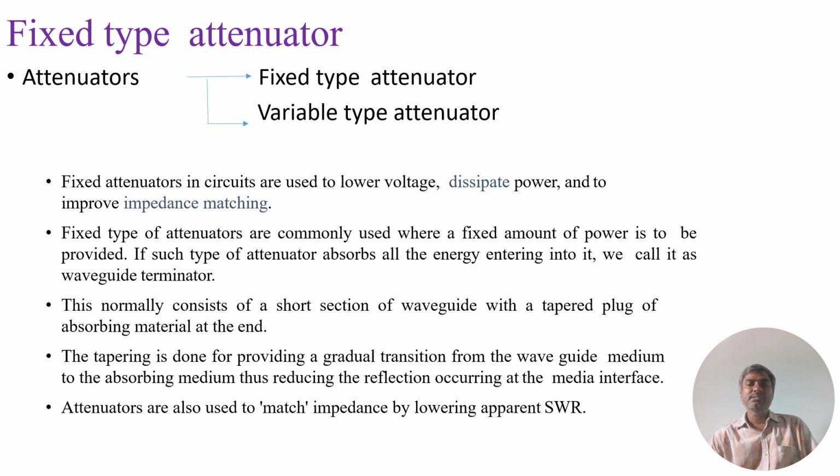The tapering is done to provide a gradual transition from the waveguide medium to the absorbing medium in order to reduce the reflection. Mainly, attenuators are used to match the impedance by lowering the standing wave ratio.